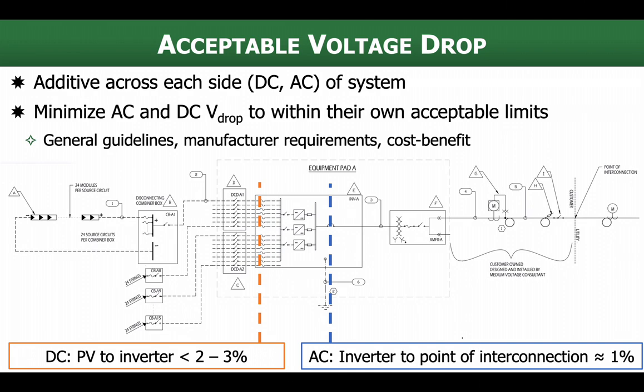The issue being that, if the grid voltage itself is high and the inverter's got to be above that grid voltage to push current towards the grid, well, now all of a sudden with high grid voltage and voltage drop, I may end up having a voltage at the output terminals of the inverter that's above the rated voltage it can operate at, right? A 240 volt inverter, if it sees 264.1 volts at its output terminal, it shuts off. That's a high grid voltage shut off.